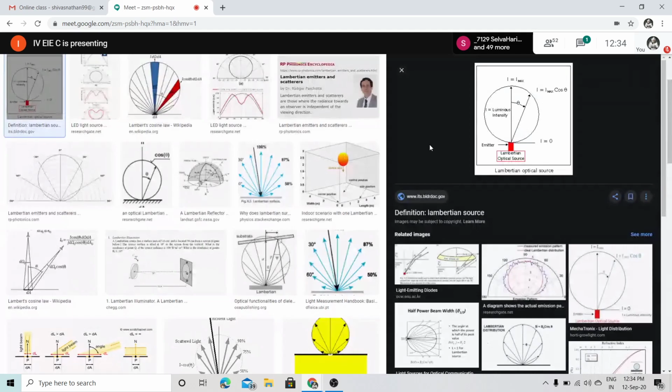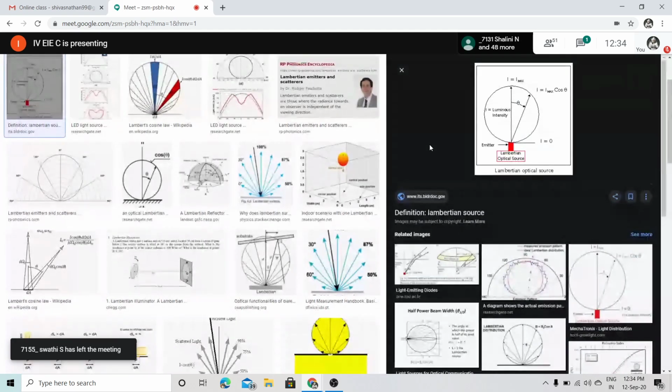Am I right? So when we speak about optic modulators, we are going to have a change in light intensity that happens because of the change in refractive index, with respect to the parameter that is varied as an input. Clear. So when the types of external modulators were discussed, we had three different types. One is electro-optic modulators based upon the Kerr effect. The second is magneto-optic modulators based upon the Faraday effect. And finally, the third is acousto-optic modulators, which depend upon the photoelastic effect.